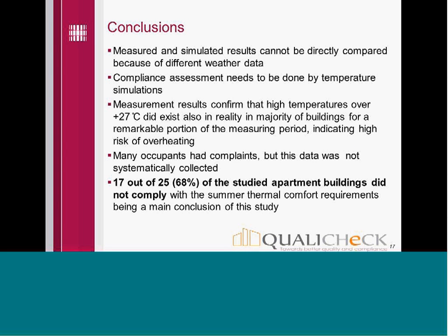To conclude, it is important to understand that measured and simulated results cannot be directly compared because of different weather data, and also because window airing can be taken into account in the temperature simulations. When you run the measurements, and for example the apartment is an empty one, window airing will not happen, and the result will be somewhat different.